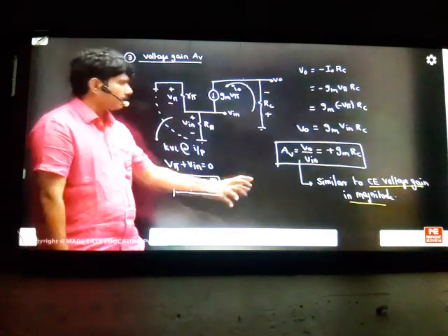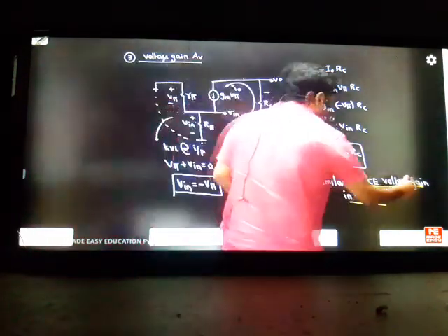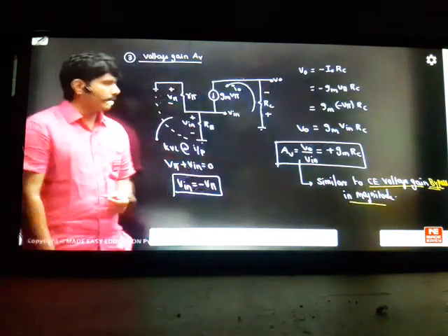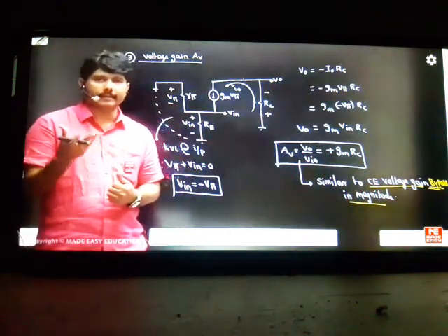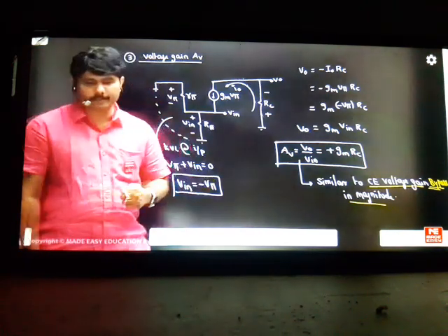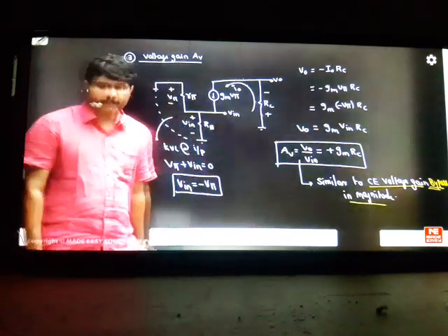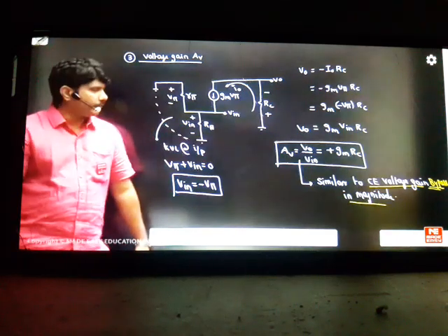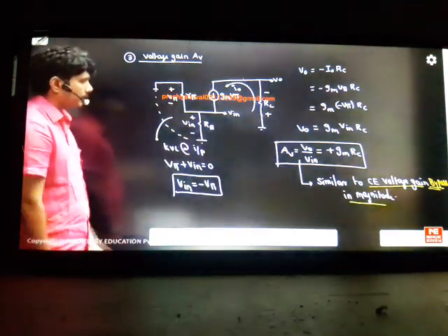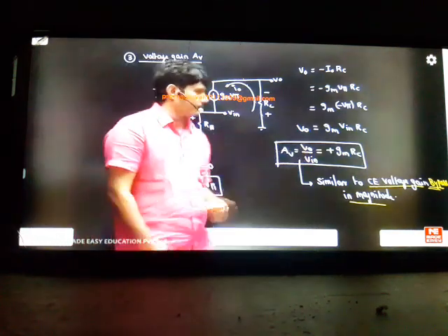So Ankum Das, I think this is exactly coming. Common emitter voltage gain, bypass. Somebody asked me a question: sir, how is it bypass? This is the meaning. If it is an unbypass system, it will give the answer GM into RC by 1 plus GM into RE. If it is a bypass, we get only GM into RC. That's why it is a bypass system, not unbypass. From the gain formula, you can understand it. It is the bypass common emitter voltage gain magnitude. And it does not have a 180 degree phase shift. It's a positive gain, not a negative gain.